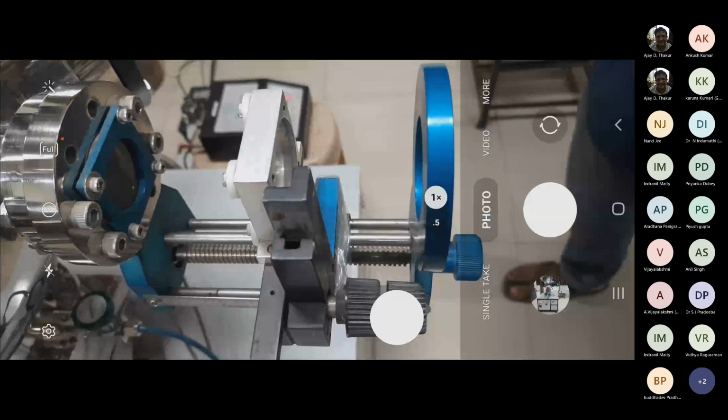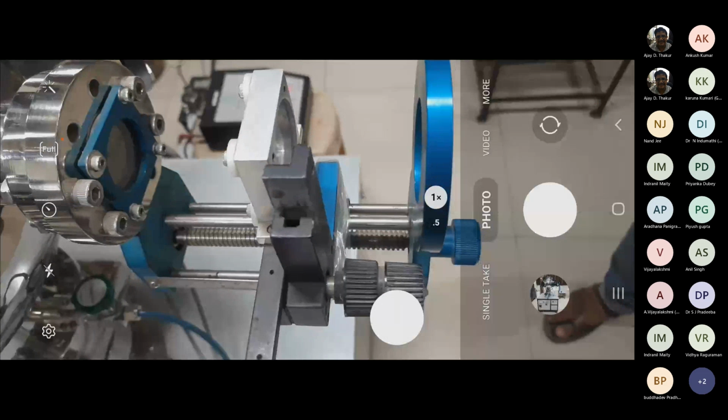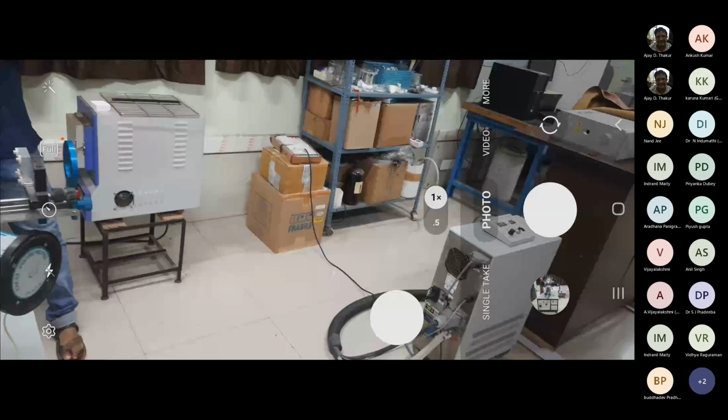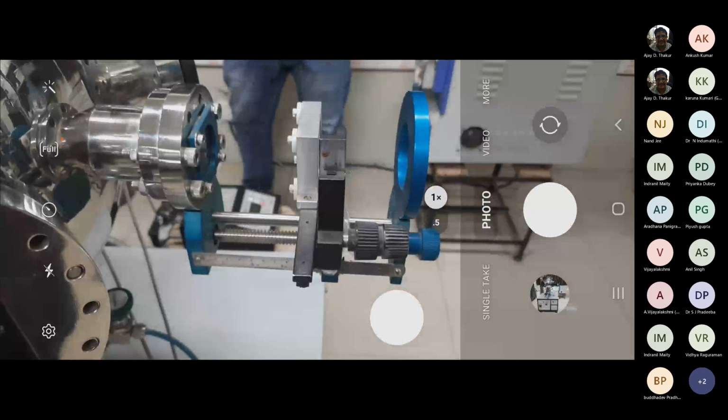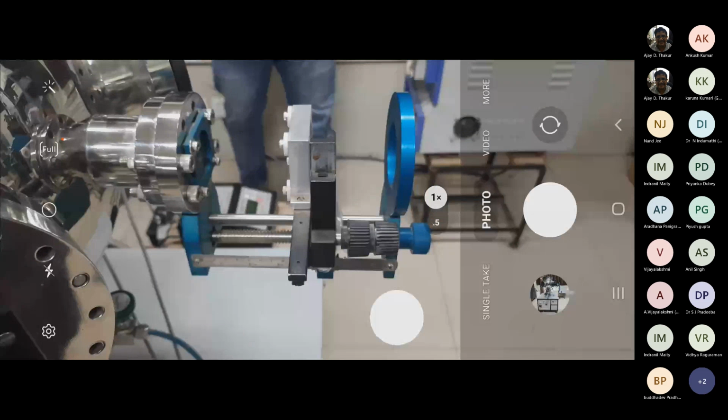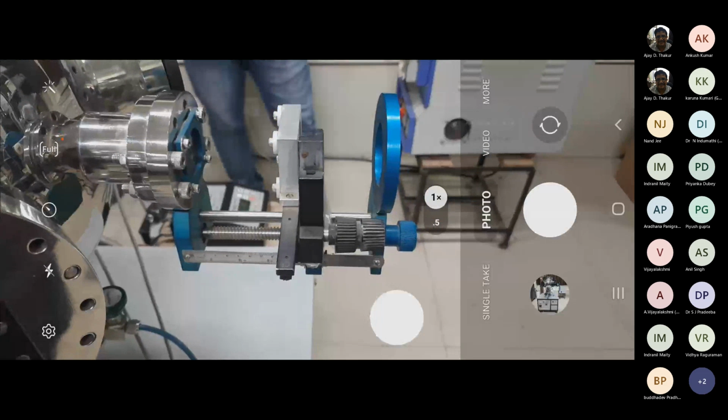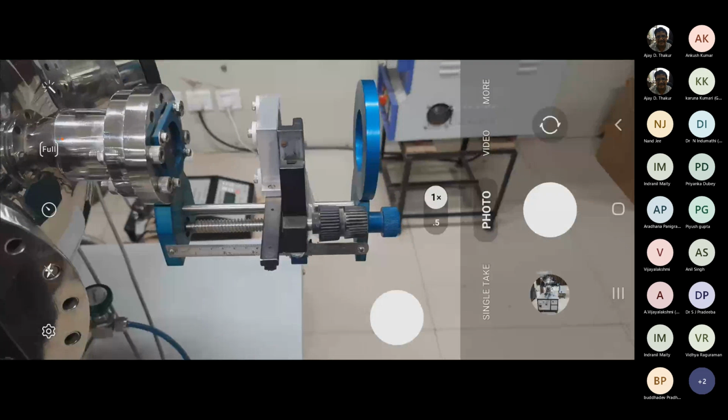So this large air gap is particularly required when we are using an Nd:YAG laser at higher harmonic. Because in such situations, this Gaussian beam profile becomes much more uniform as it travels through some amount of distance. If it was very close, then the pulse to pulse variation would have been larger. So in order to avoid that, the laser pulses are allowed to travel some distance in air.